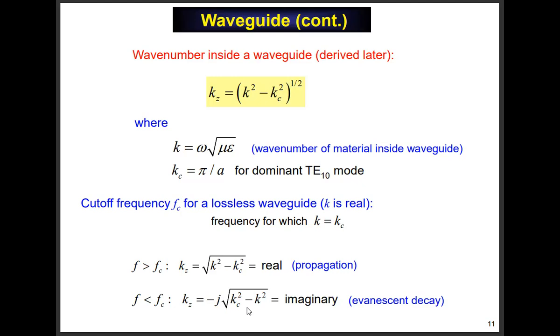So it's really interesting that in a rectangular waveguide, you get this very important frequency called the cutoff frequency. Above it, this TE10 mode can propagate beautifully. Below it, it'll just attenuate and it's useless.